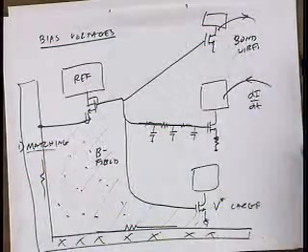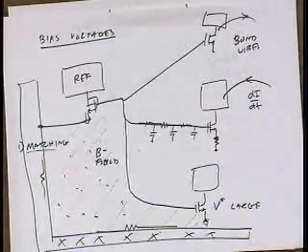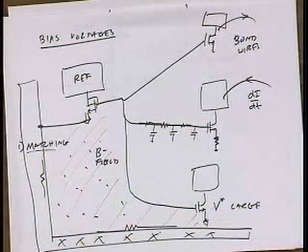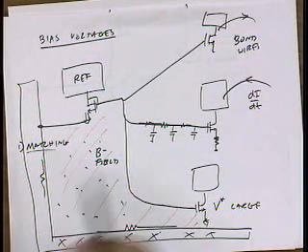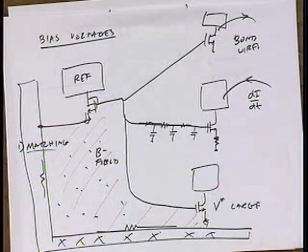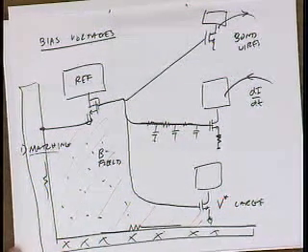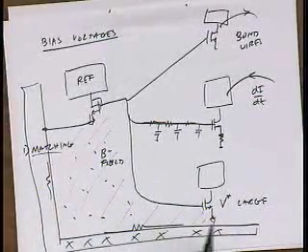So it's really bad if the output stage is coupling back into its own bias stage, right? It's a feedback path. It might cause you to oscillate. It might produce some mysterious spur on your spectrum analyzer that you just can't trace, right? So what's the solution to this problem? Let's get someone else. Okay, anybody can think of a way to still route this voltage but eliminate this large pickup?